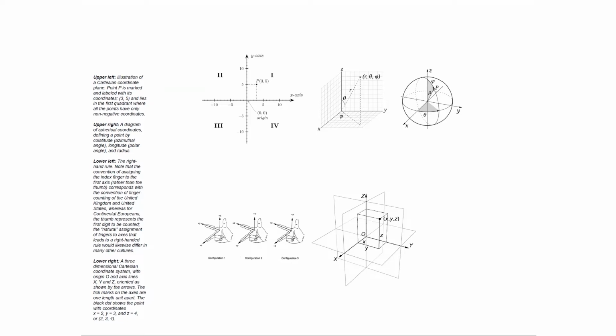This is just to help us navigate these three-dimensional coordinate systems. Again, in Rhino, when we define a plane, we define only two axes, and the third one is then given according to this right-hand rule. Technically, z is the cross product of x and y.